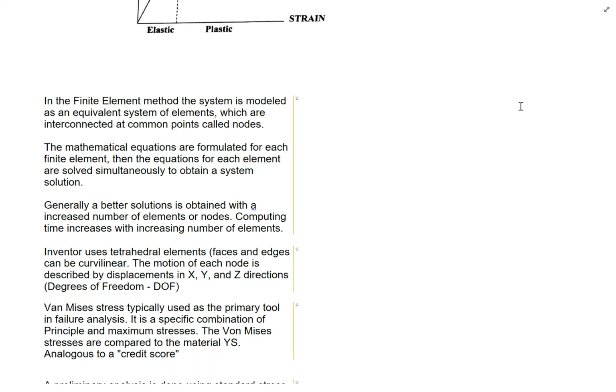So if I've got, like I showed you on that shaft, an area that I anticipate having a higher than average stress concentration, I can selectively mesh that tighter and wind up with an accurate solution. So again, that's really fairly recent. You can take a standard engineering grade laptop and do some fairly sophisticated stress analysis on that. So, fairly new thing.